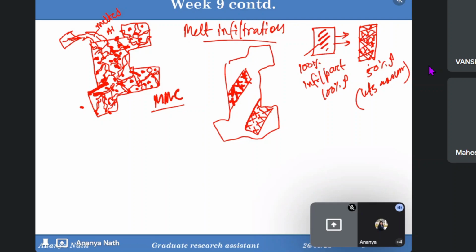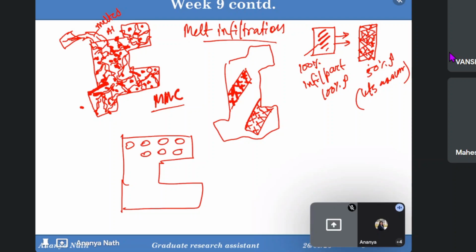But here in the mold, you are placing the particles. So there, according to me, you need to make this type of lattice structures, and there you can use surface type lattices instead of rod type lattices. So in a mold, this is the mold, you have to place the SiC particles, for example. You can make the SiC particles spherical or plate like structure instead of some irregular structure. But anyhow, you have to place it without any help of supporting structure. So they should have the self-supporting structure like this.